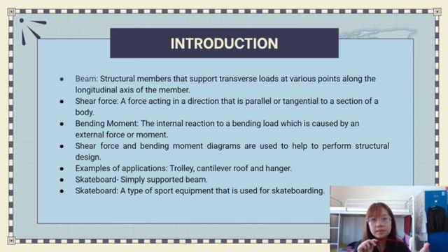So, what are beams? Beams are defined as structural members that support the transverse loads at various points along the longitudinal axis of the members. Besides, shear force is a force acting in the direction that is parallel or tangential to a section of a body, while bending moment is the internal reaction to the bending load, which is caused by an external force or moment. Shear force and bending moment diagrams are used to help to perform structural design.